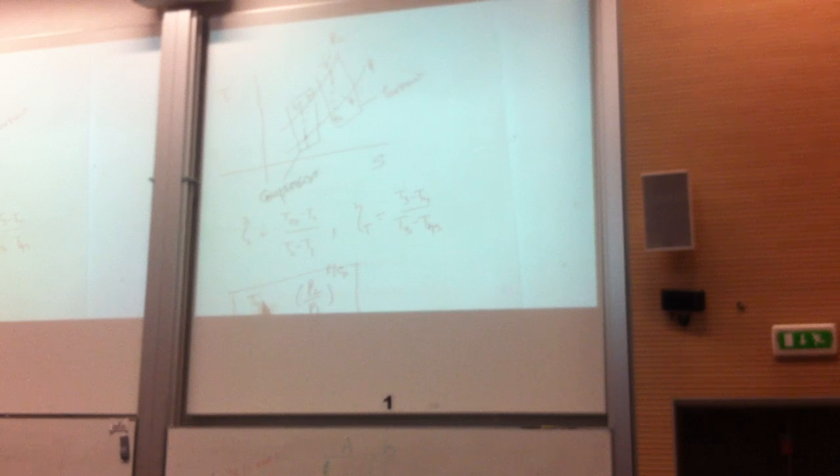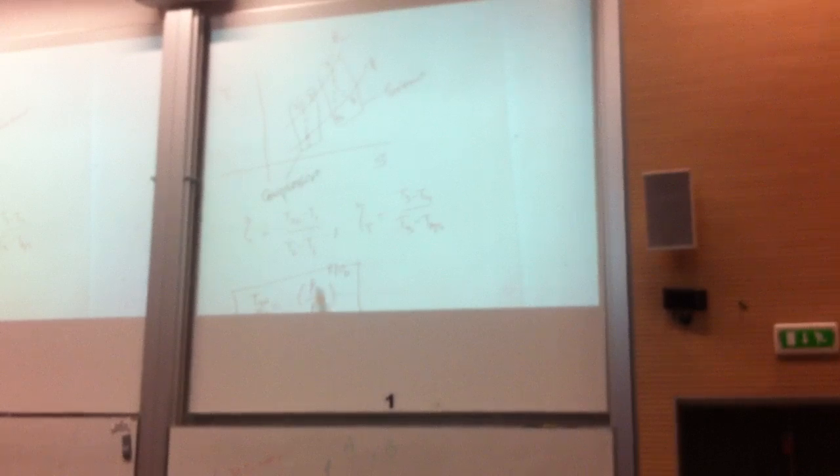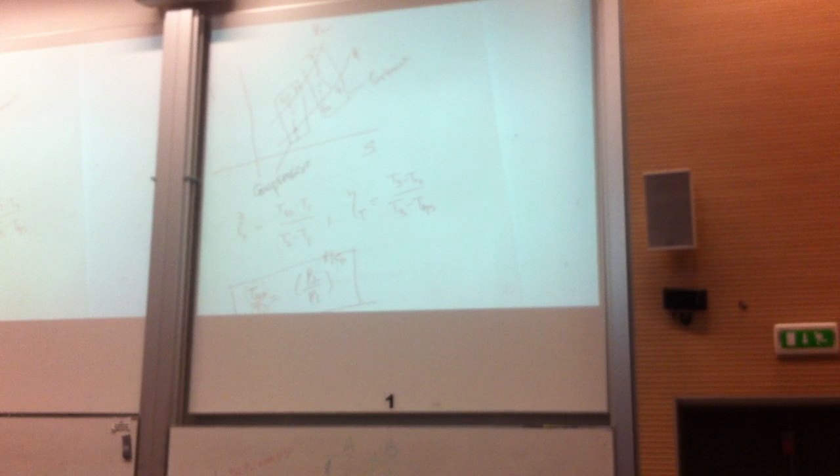So this is, for example, T2S. Now you have got T1, you have got the two pressures, you have got R, you have got CP, you can work out T2S. If T2S is calculated, just put T2S over here, efficiency is known, T1 is known, T2 can be calculated. The same holds for the turbine as well. That's done. Finished. Just a 35 minute job.